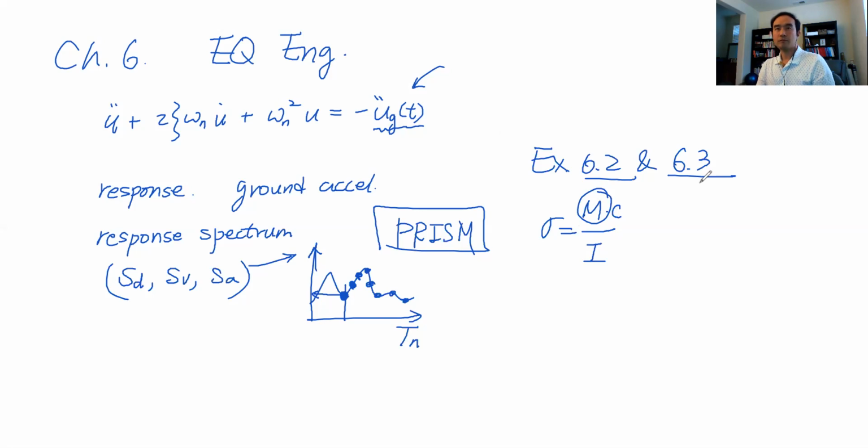The conclusion was we had a benefit of using that larger steel pipe in terms of the peak deformation, but in terms of the acceleration, which is critical to calculate the bending moment and the bending stress, it was even worse. So these two example problems will be good problems to exercise and prepare for the final exam.